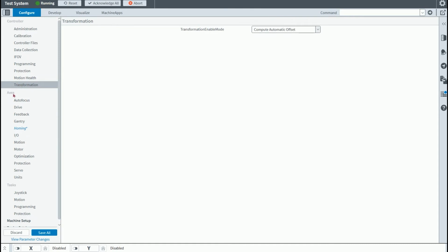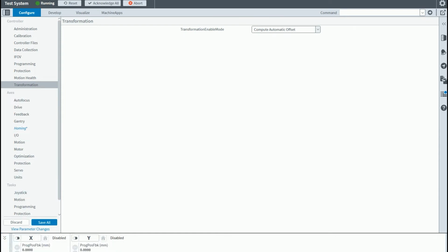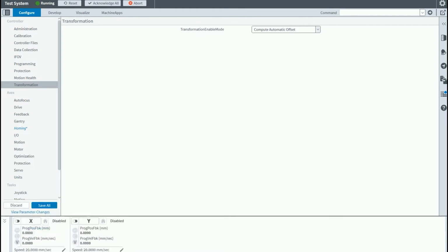There's several different axes parameters that can be configured as well. We just went through many of those in our example and machine setup. And then finally, the same for axes. You might have noticed that after we went through machine setup, X and Y axes were populated on the axis dashboard. You can also enable your jog buttons, where you can enable your axis and jog forward, jog reverse right here from this screen. And then you can also home the axis as well.